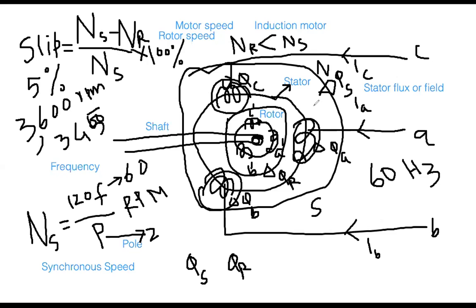And keep in mind, there are no physical magnetic poles. Therefore, this pole number in the equation is developed internally, intrinsically. You can't see it. Pole number could be 2, 4, or 6, depending on the coil arrangement. By changing the coil construction, you can change this number. Keep in mind the minimum pole number must be 2. You all know every magnet has at least a north pole and a south pole. So the minimum is 2; it can be 4, 6, depending on the motor.